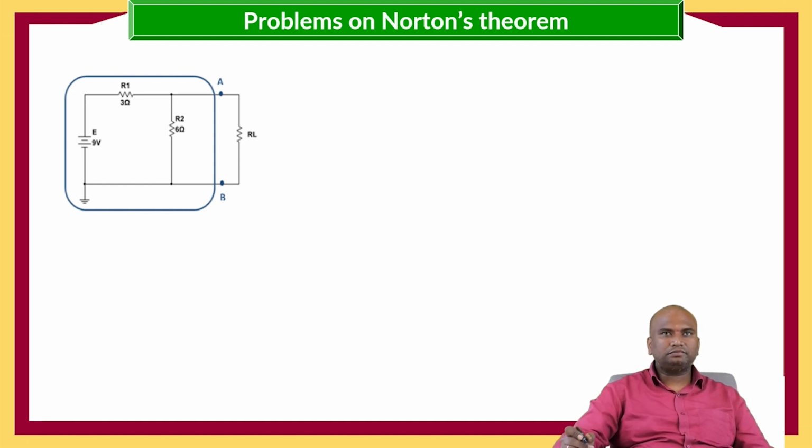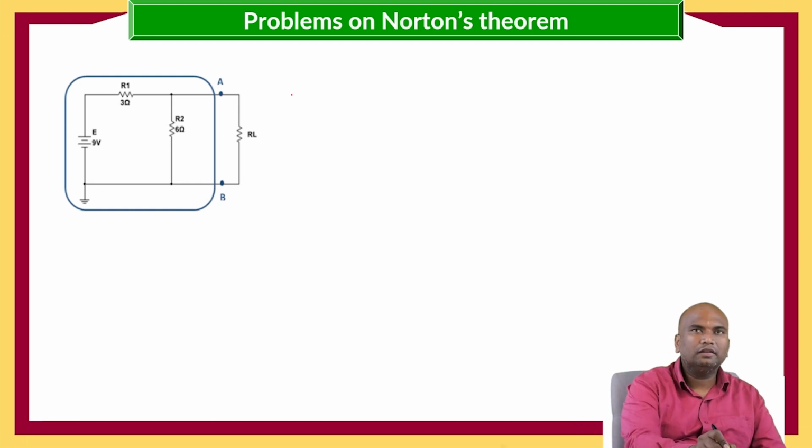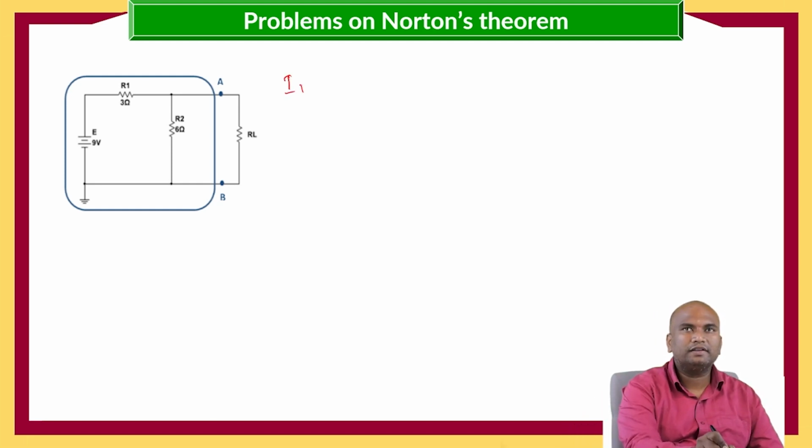Here, for calculating Norton's current, I am replacing the load resistance with a short circuit.